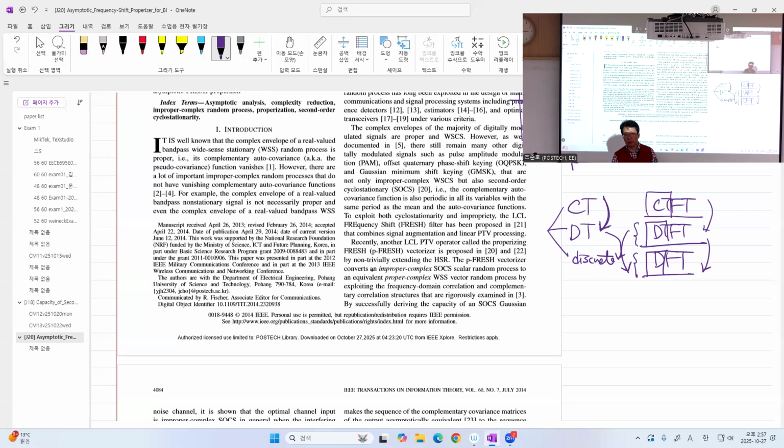So basically, our error control coding and modulations try to uniformly spread our signal power as far as we don't know what will happen. Of course, if we know what will happen in a channel, we want to exploit the channel's property. That's why we do water filling. So in a better channel, we put more power. In a bad channel, we put less power. That is water filling. So be careful. Sometimes we have a lot of information about the channel. In that case, we may exploit the channel's selectivity. But in some cases, that is almost impossible. In that case, we'd better spread our energy through all the spaces.